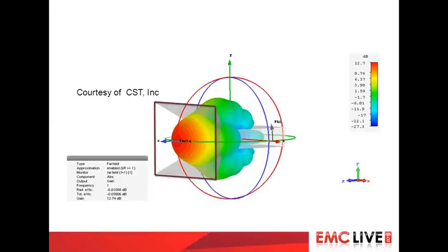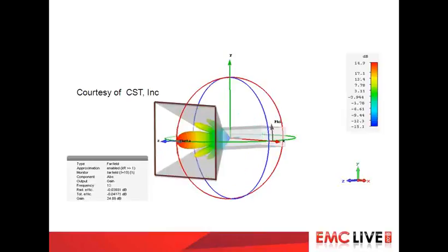How does this rudimentary flared waveguide antenna work at 10 gigahertz? Try and remember this first picture. There's 10 gigahertz, and when I read the gain in the very bottom line there on the left, I read 24.89. That's a phenomenal increase in gain. Something you don't really want, but it's a very rudimentary antenna. And there's a price to pay.